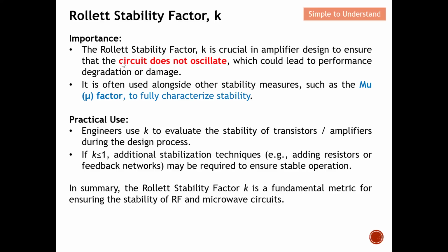So, for example, we need to ensure that the Rollett stability factor is more than one, so as to ensure that the circuit does not oscillate, which means that we are protected from any potential damage to the circuit design. It is also often used alongside another stability measure, known as the MU factor, so as to fully characterize the stability.